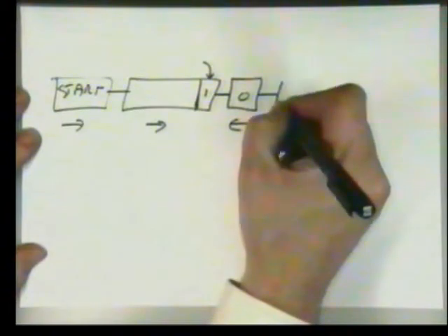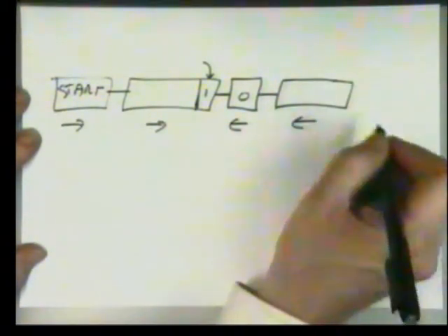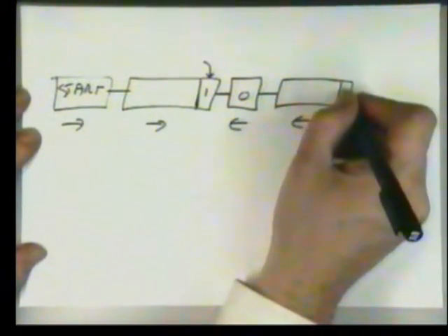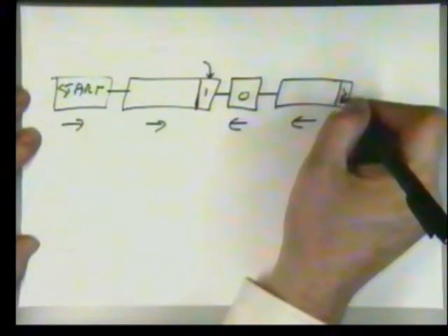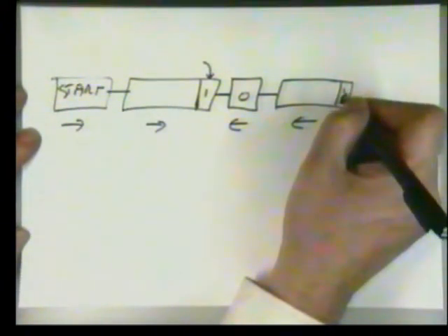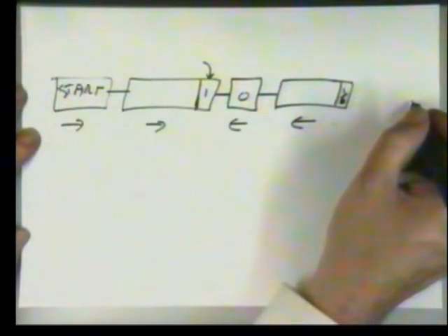But now the next operation will be a transfer of 8 bits from the slave back to the master. And again, the slave would say 1 or 0, depending on whether it wants to now send another byte of data or not. The state of this bit determines the direction of the next operation.